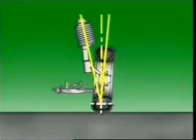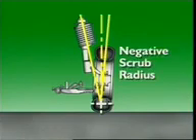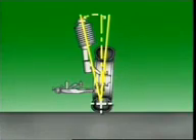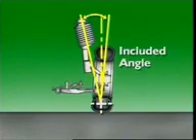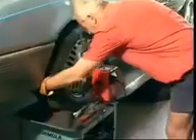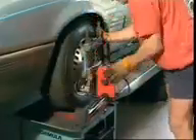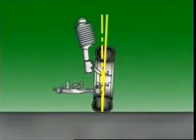It intersects with the camber line drawn through the tyre and the wheel. If these two lines intersect at the center of the tyre at the road surface, then the vehicle is said to have zero offset or zero scrub radius. If they intersect below the road surface, then it has positive offset or scrub radius. If they intersect above the road surface, then it has negative offset or scrub radius.